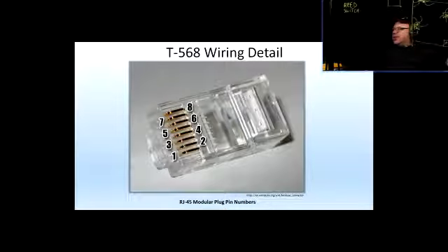All right, so the pins we count in this way here. Remember when we were doing testing and it showed that one wire is broken or one is missing? Just by looking at the screen, I could say, okay, that's white, orange, because I was able to count the pins on the wire map that the tester would display.